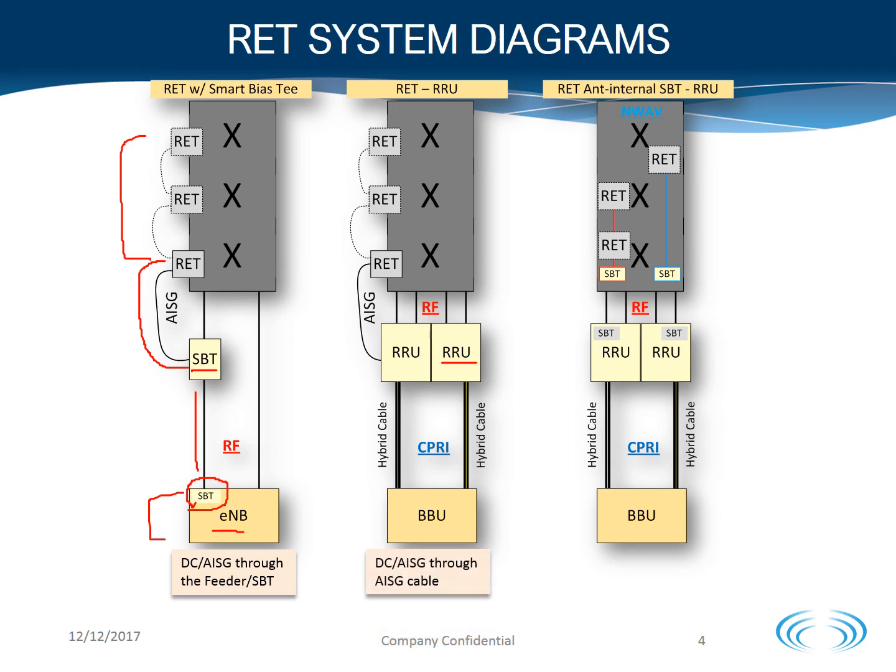RET system example 2. The RRU is mounted up top, and the RET port on the RRU will have an AISG cable connected between the RRU and the RET. That's how the DC and AISG signal is being sent to the RETs. Again, follow the RFDS for daisy chaining.